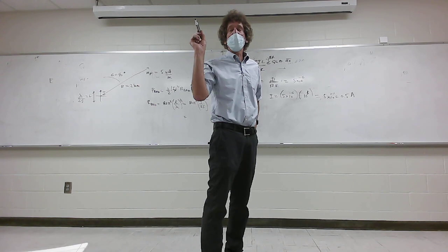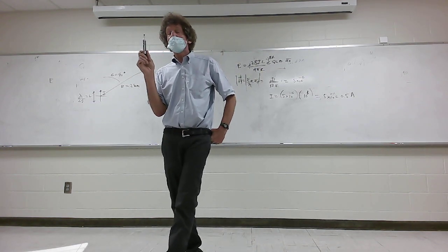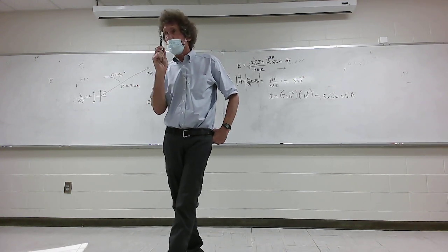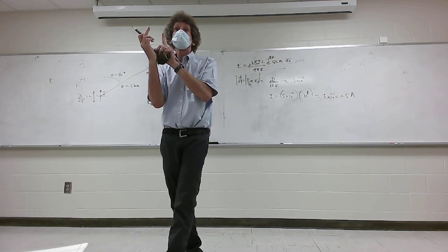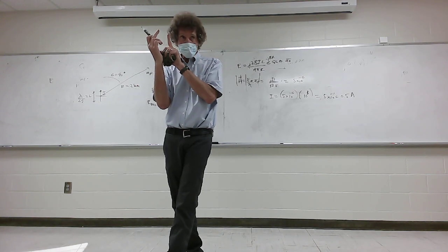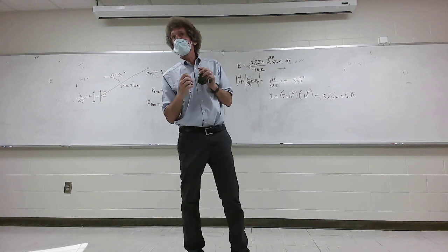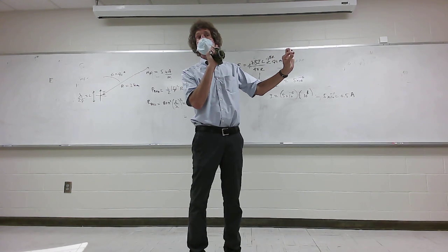I did paste the equations for the H field and E field for loop antennas. Usually, hear me now, when you're in the field, you won't have a single loop, almost ever. What you'll have is a whole bunch of loops where the diameter is much, much smaller than the wavelength. These are small electrically, and they'll have a whole bunch of loops. The reason is this: each one of those loops is like adding an antenna in series, and it increases the radiation resistance.